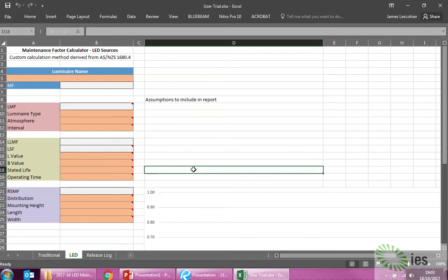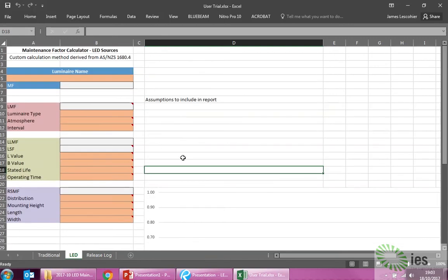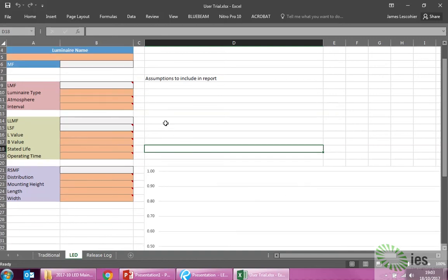And so I've tried to represent that as much as possible on this chart, but you don't see it actually when you plug in that number there. You actually mostly see it in my chart based on the deaths. I assume that if 50% of the luminaires are below their stated value at L70, they're actually degrading faster than the ones that are only 10%. So I'm treating it as a degradation past its rated life figure, is how you see it on here, as well as it actually does affect the crossing point.